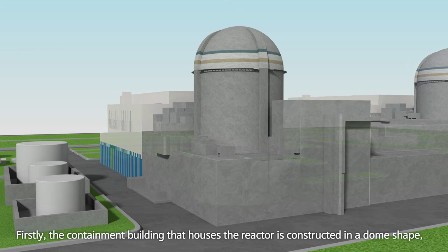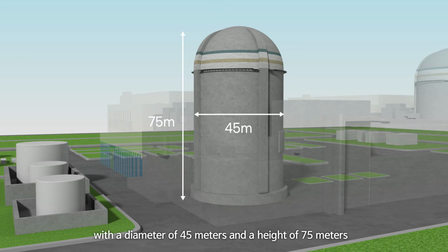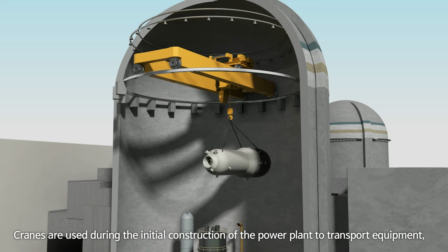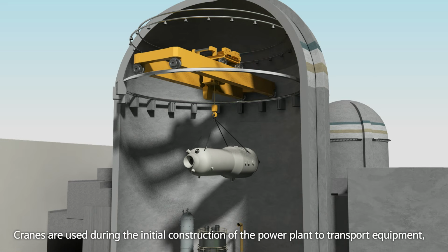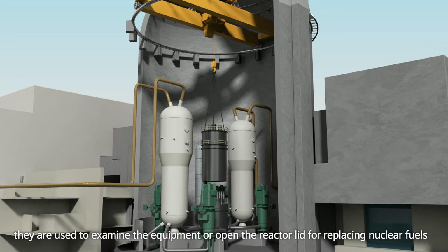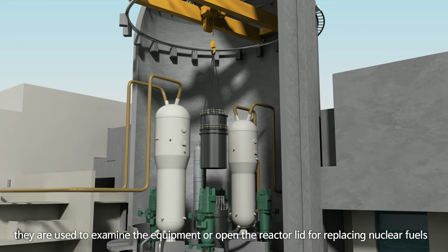Firstly, the containment building that houses the reactor is constructed in a dome shape, with a diameter of 45 meters and a height of 75 meters. Above the building there are cranes. Cranes are used during the initial construction of the power plant to transport equipment, and during regular operations they are used to examine the equipment or open the reactor lid for replacing nuclear fuels.